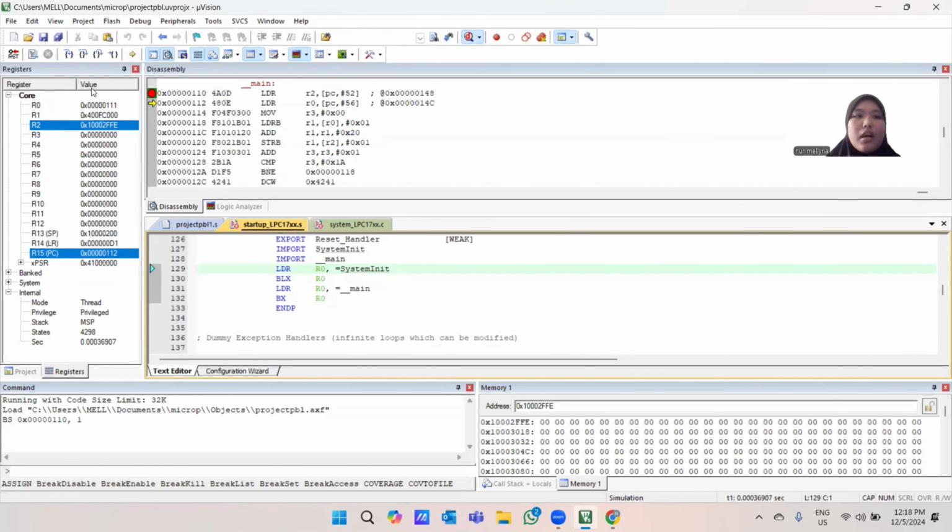So this shows that the coding works successfully, and the data has been transferred successfully into the memory. The result analysis and implementation show the successful execution of the assembly coding, converting the uppercase to lowercase and storing them in memory. So as we can see, the first data address, which is 2FFE, shows the sequence, and then it increments up to the last address, with the last data being 7A, using the first data 61.